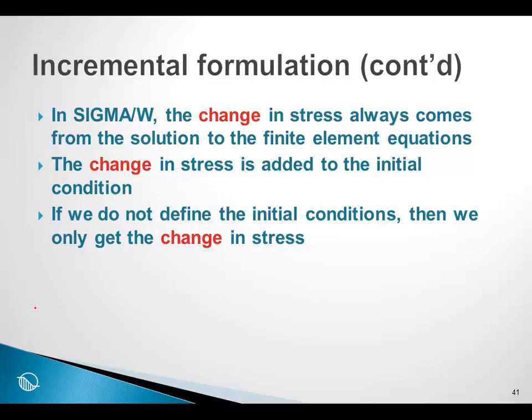In Sigma/W, the change in stress always comes from the solution to the finite element equation. The change in stress is added to the initial conditions. If we do not define the initial conditions, then we only get the change in stress. So in our footing analysis so far, we did not define initial in situ conditions, and therefore we only got, in our analysis, the change in stress.